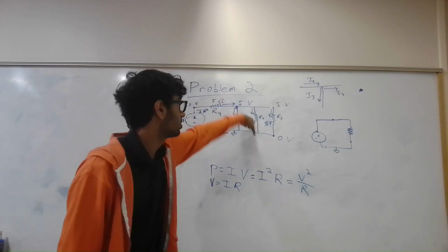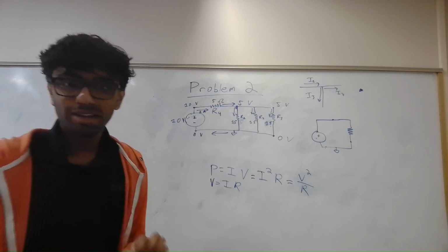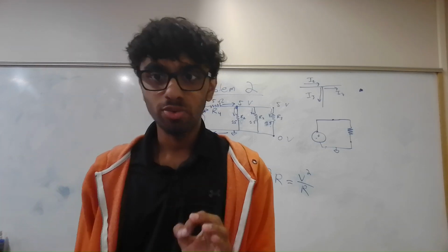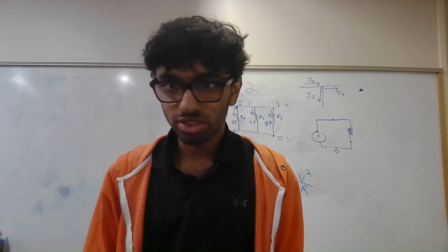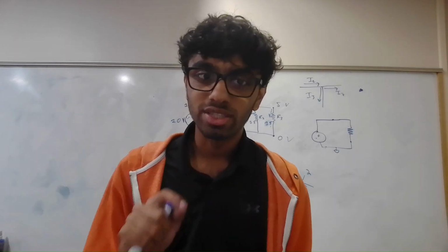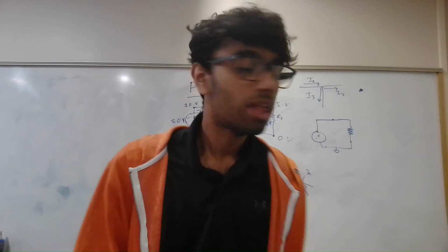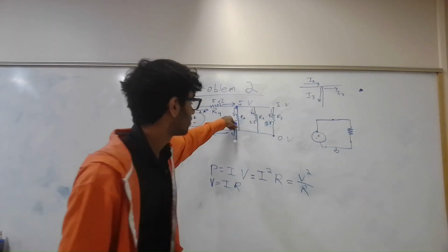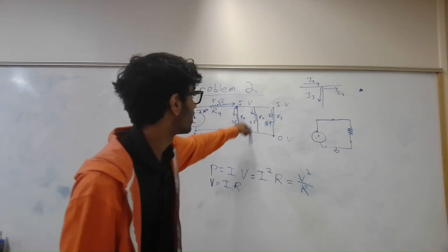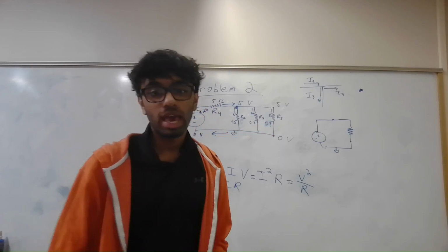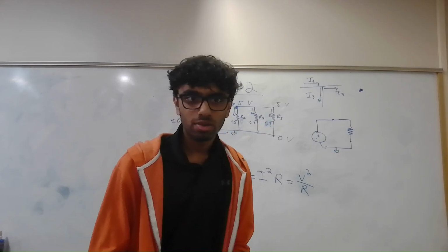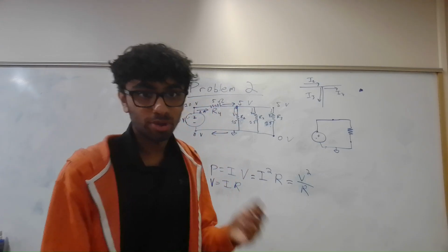It's all going to go somewhere. And because the three resistances are equal, just by symmetry, since this is a totally symmetric situation, we know the currents through each of them are also equal. Therefore, it's a third of an amp through there, 1/3 of an amp through there, and 1/3 of an amp through there. Okay? And now that we've done that, we've answered that question.